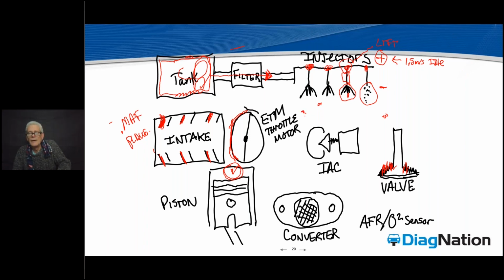All right, 1.5 milliseconds. Now, my throttle motor at the same time was at 3% when it was new. Now, I get this car in front of me, it's 60, 70, 80,000 miles, whatever it is. It's got the idle shake, it's got drivability issues, maybe they're complaining of poor fuel economy. And I now look at this throttle motor and it's at 6%. Why? Because as this deposit builds up, all it can do is open, open, open as that deposit gets worse.